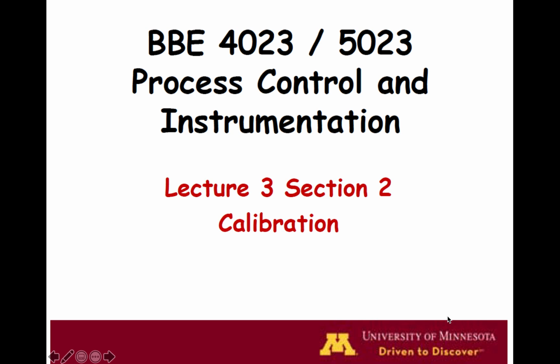Welcome to the second and last video for Lecture 3. In the first video, we talked about uncertainty analysis, and here we talk about calibration. Specifically, we will introduce a couple of concepts related to adjusting instruments and the procedures for calculating linear calibration curves using a least squares-based procedure.